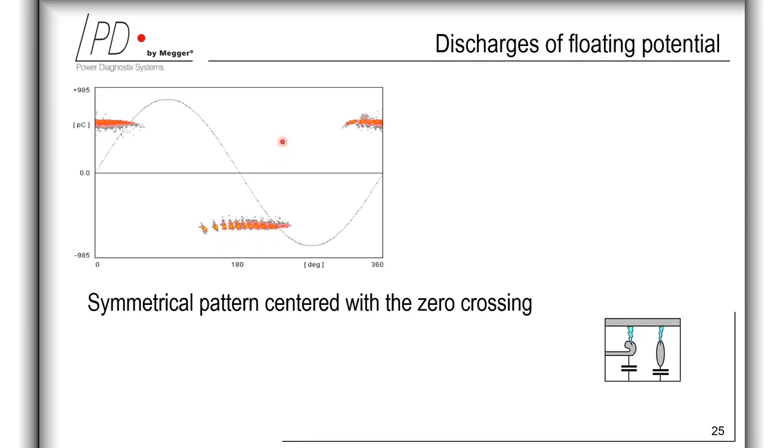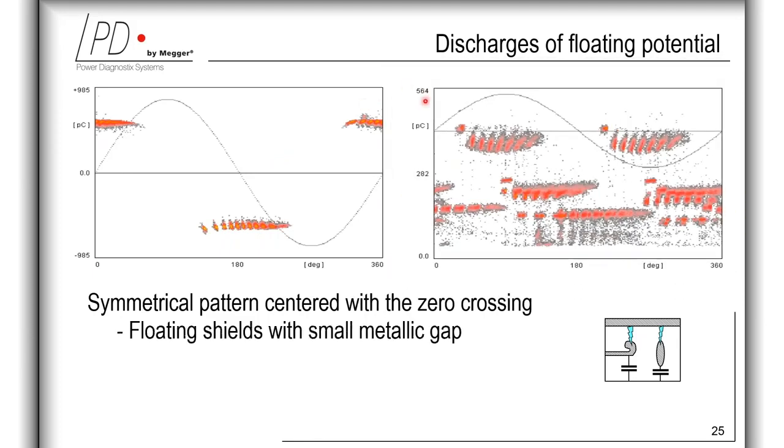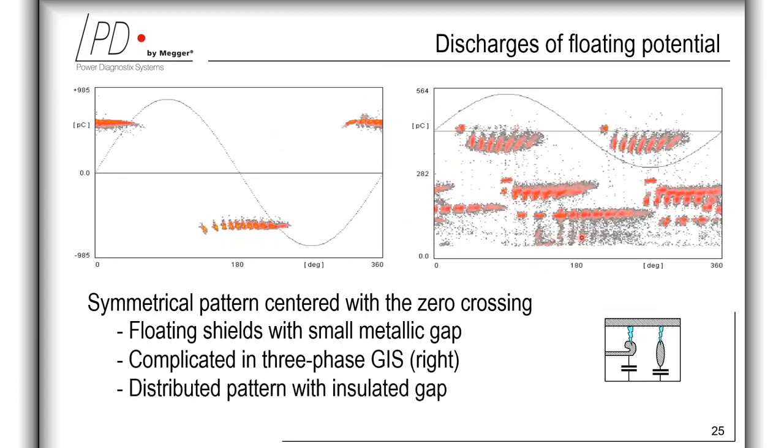Whereas this pattern on the right-hand side is from a gas-insulated switchgear. Here you can separate each of the 3 phases by means of a 120-degree phase shift. And here each stripe represents the delay in the partial discharge signal. And this is due to the availability of starting electrons at the point where the avalanche starts. And compared to the pattern on the right-hand side, here you have low availability of starting electrons.